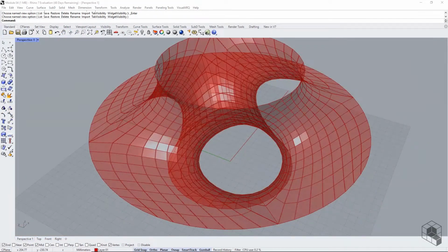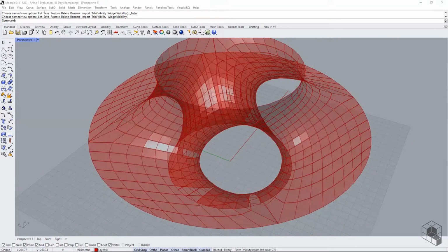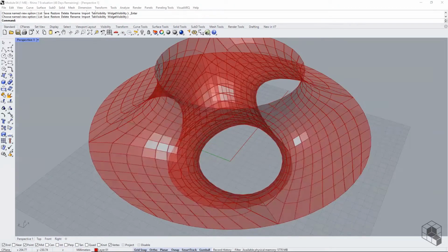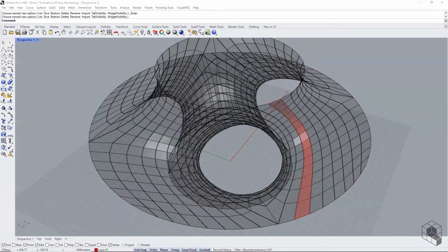For the warp strips, we would like the insets like this. And for the weft strips, we would like the strips to be like this. Since there is no direct way of doing this, we will have to start by extracting the internal edges from each strip, and the shorter naked edge. Let's assume this strip, and these are the lines extracted from the strip.